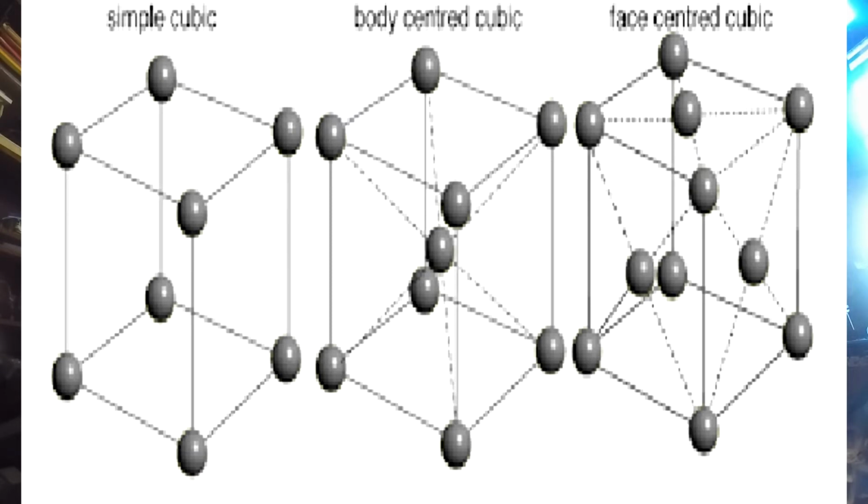Given the fact that this is not a course in metallurgy, I will use the simple cubic shape as my example of how atoms form dendrites. Now, this may be a new word for you, dendrites. Dendrites are the form that metallic crystals take when the molten metal cools and solidifies. They look very much like ferns one might see out in nature, out in a forest somewhere. Okay?